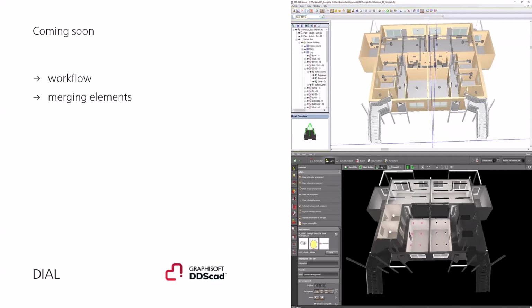DIALux, the way you create a building inside, is based on merging elements. That means if you place a wall or 4 walls on a surface, then DIALux automatically identifies the connection between those surfaces. We have seen them in our previous versions as these green elements you have seen in the CAD element. This is because in the past we had a look at the correct calculation, and for the correct calculation it's very important that all the surfaces are separated, so you receive an exact, detailed, different calculation result on each surface in the project.